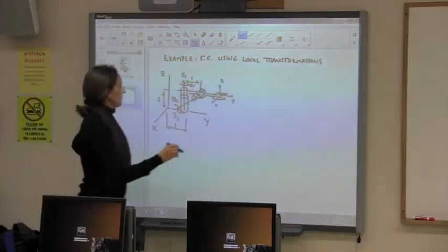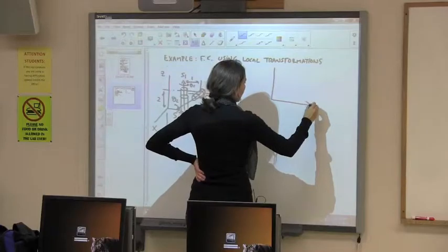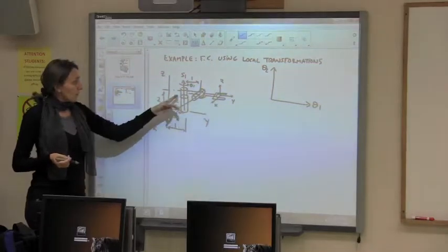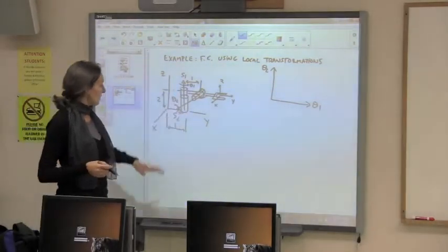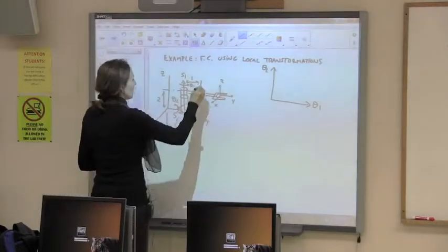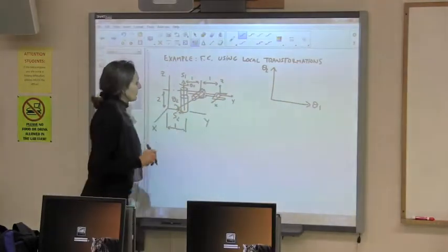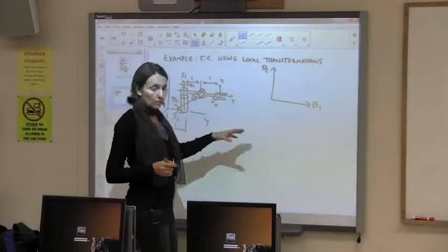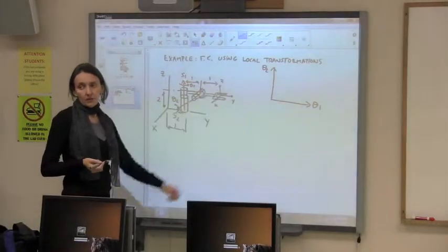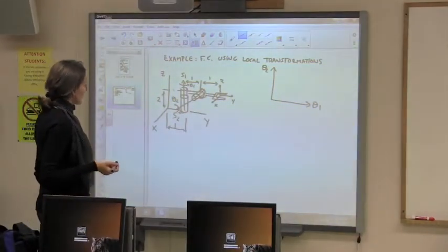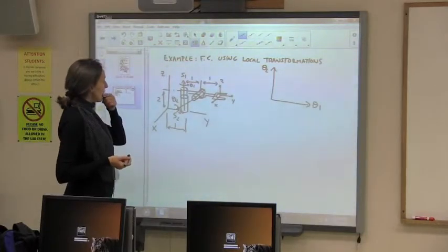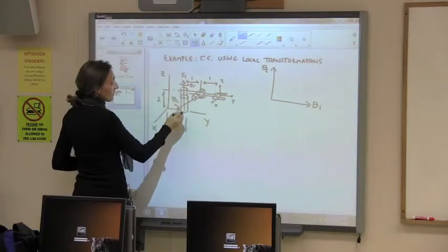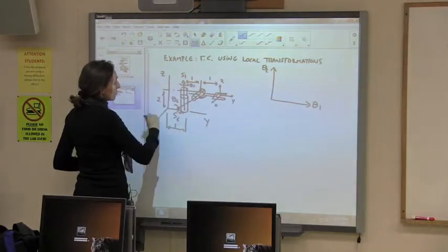Right? We can write any configuration as a point with a given value of theta 1 and a given value of theta 2. Okay, this robot is fixed. We know what it is. Oh, this distance could be 1, 2. And now we need to pass from this joint space, we need the map to the position of this end effector, location and orientation. And if we do the local transformation, first we have to move from this local frame to a local frame here, at the first axis.